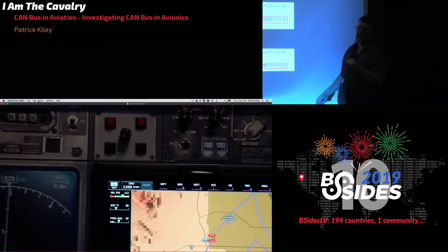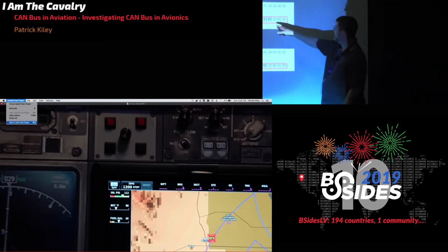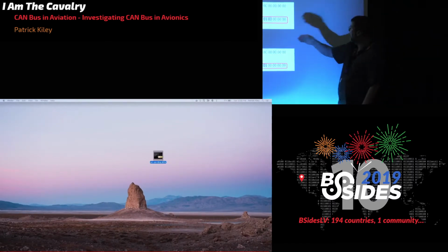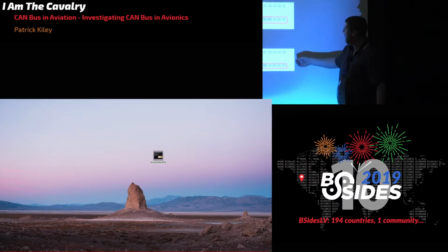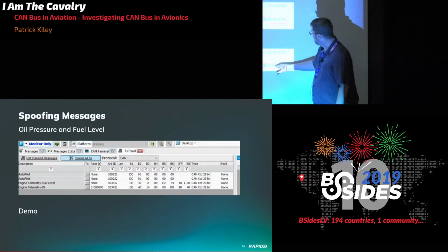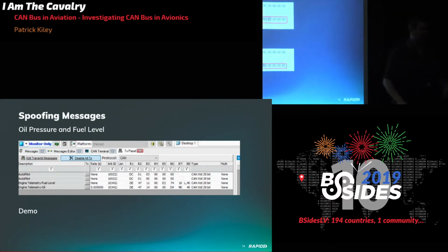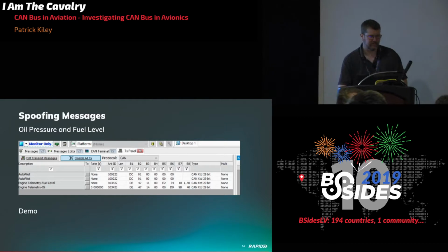If I disconnect one servo from the system and remove it from the configuration, you'll see 0101. So each individual bit in the hex message represents a servo to tell it to turn on and off. And then when you disable it, it's just 01 again, and then 00 saying no servos. And that'll turn the autopilot system on and off.